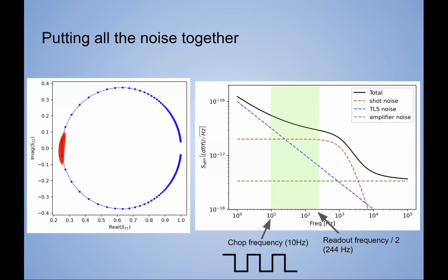And that's really what I was saying. For one over f noise, you sample at a gigahertz. Right, but then it's limited by this chopping frequency too. It's how fast can you move a blocker in front of your detectors. Typically 10 hertz seems like the practical limit. Right, because you're integrating all the way down. Then I guess at some point you have to care about drift too, and you have to calibrate your detectors once in a while. It's a different problem.